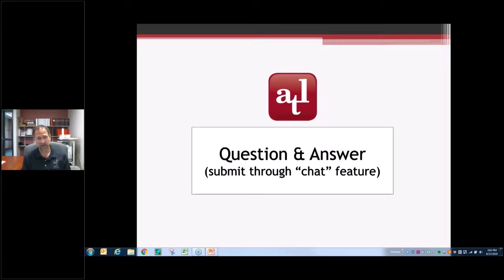A lot of these other methods you could still use to evaluate early concrete. Ultrasonic pulse velocity is probably one that I wouldn't use to evaluate early age concrete, because that might give you some values that are a little higher than they really are, just because the early age concrete still might have a lot of moisture in it. It's still kind of green and curing.